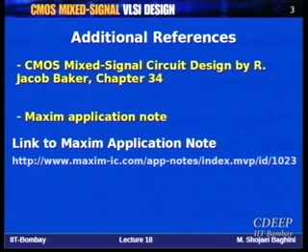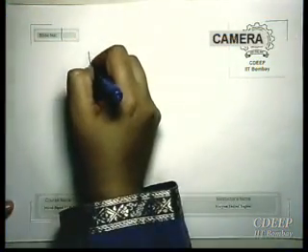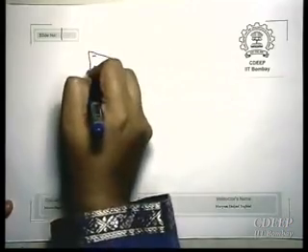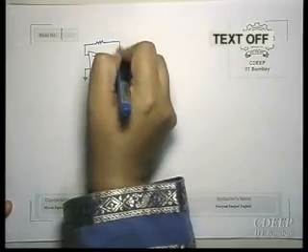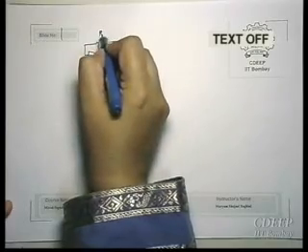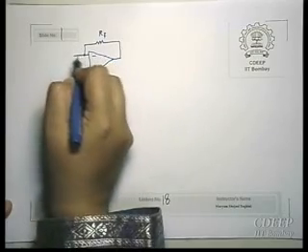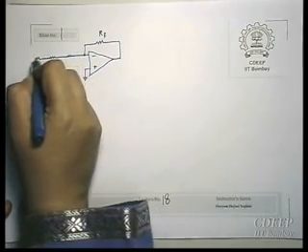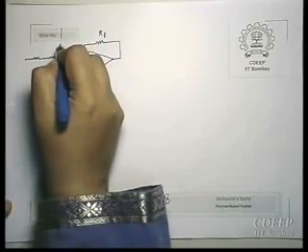And I will just tell you one small configuration. It is easy to understand, just as an alternate for DAC. I don't explore it, it's very easy to understand. It is just one another architecture. One architecture we explored in the last quiz, right, the R2R ladder for DAC. So similarly, you consider the same R2R ladder. Because here we have current sources, I put them over here.